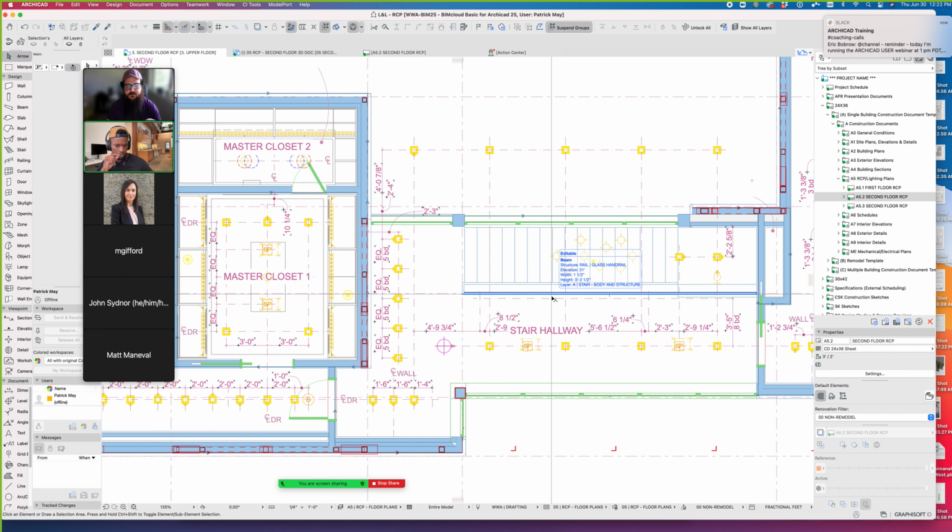I think that having the ceiling registers, HVAC, ductwork, things like that that penetrate the ceiling, could benefit from showing those as the actual projected instead of symbolic view, because a lot of times we don't even have a symbolic view for those things. There are objects that we use for ceiling registers, but it makes sense just to show the full extent of those elements along with the boards and or beams or ceiling treatment that associates with them. So that stuff can all go on to the 3D document as well.